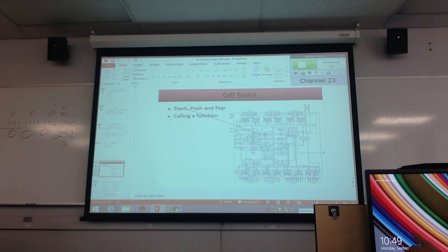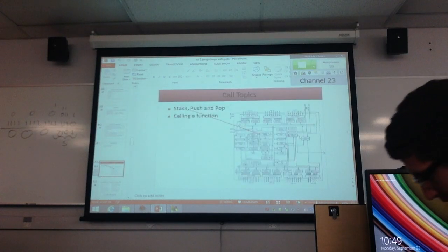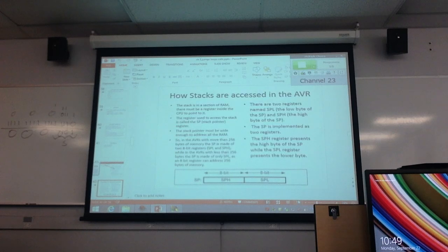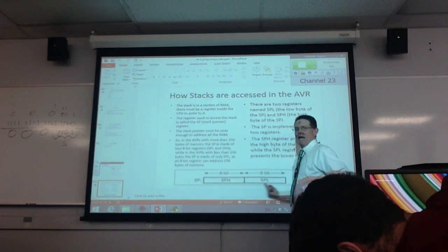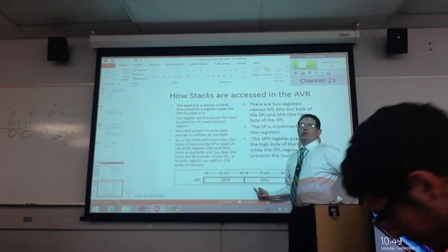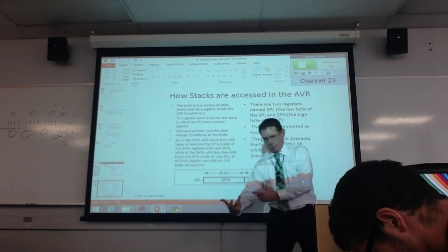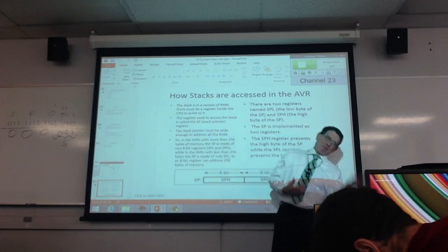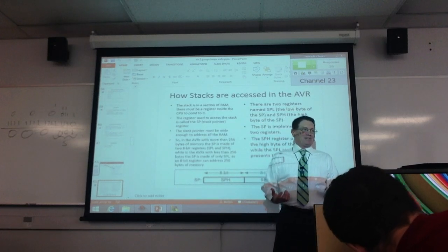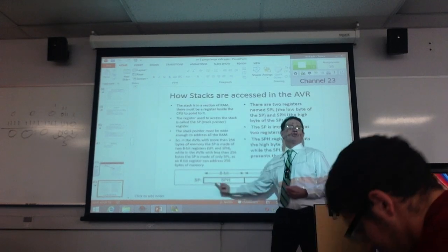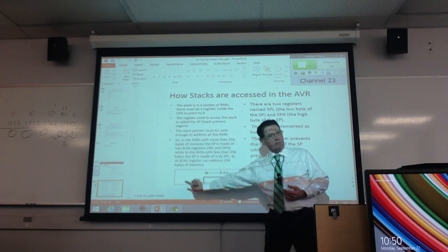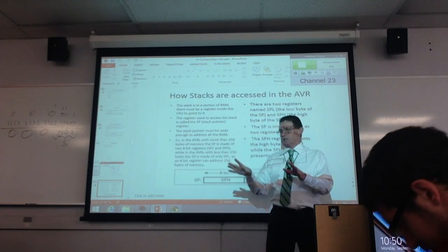So basically, the idea is we're going to be looking at a 16-bit stack pointer. Now again, this stack pointer is in SRAM, but it's holding the address of where I'm going to be going over in Flash. It's 16 bits, but we can extend this out to 22 if we need to. Right now, we're only going to be worried with 16 bits.